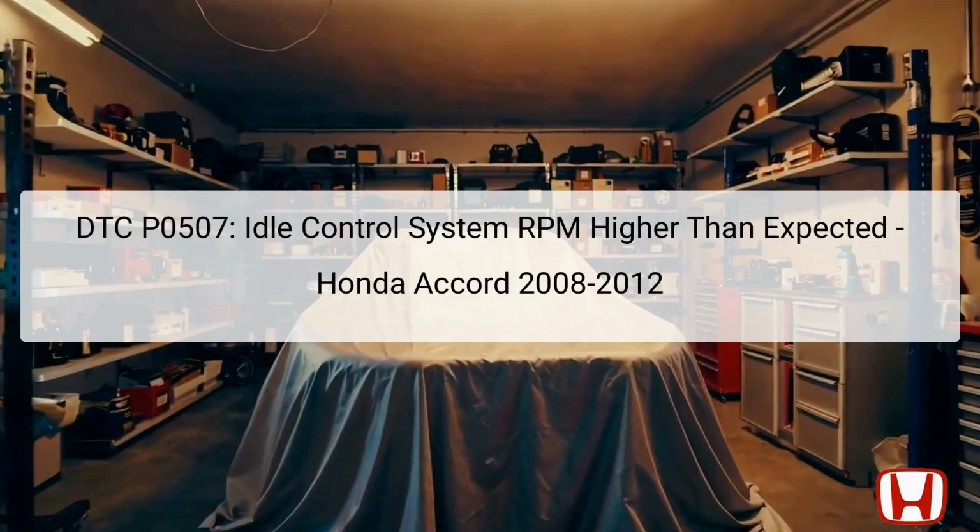The DTC P0507 signifies an issue with the idle control system in the Honda Accord models from 2008 to 2012. Specifically, it points to the engine's RPM being higher than expected during idle conditions. This can lead to various performance issues, including stalling or excessive fuel consumption, as the engine is unable to maintain a steady idle speed. The primary components involved in this DTC include the Engine Control Module, ECM, the Idle Air Control Valve, IAC, and various vacuum hoses and valves that regulate airflow and pressure.